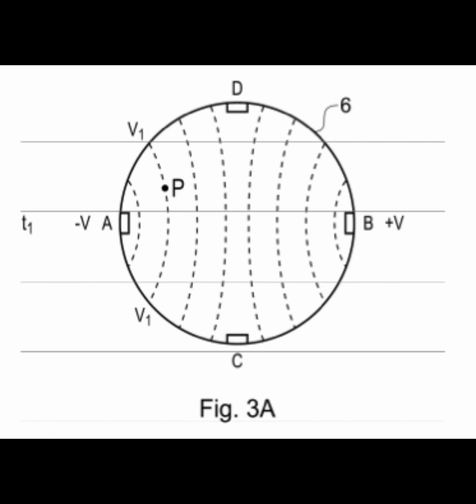The actuator comprises a conductive element at one of its ends. When the conductive element is in contact with the resistive layer, it picks the voltage off the resistive layer at the contact point. The voltage picked off is characteristic of the position of the actuator.